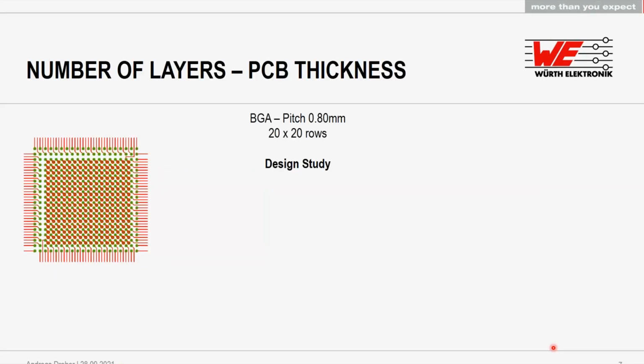So the SSOP components are maybe not the most complex parts. Typically, the most complex components on an assembly are BGA components. The BGA components have the solder points underneath them, and we see here a typical layout. I would show you an example where we go through the fan out necessary for a BGA with conventional mechanical through-hole drilling.